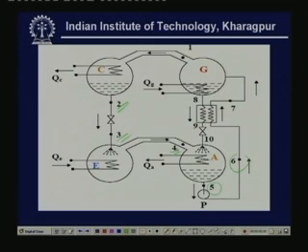Point 6 weak solution at generator pressure. Point 7 preheated weak solution at generator pressure. Point 8 strong solution at generator pressure and generator temperature. Point 9 is strong solution, so now cooled strong solution still at high pressure. Point 10 is the strong solution at evaporator pressure.